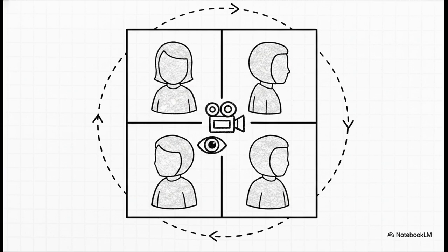Next up is step 3. Test from multiple angles. We're working in 3D, right? Which means a fantastic silhouette from the front might look like an absolute mess from the side. You have to rotate your camera. Check the front, check the side, check a 3/4 angle, maybe even throw in a dramatic low shot. Because if your character becomes visually confusing the second the camera rotates, then either your rig controls or your posing workflow really needs to be refined. A truly strong pose holds up its clarity across multiple viewpoints.